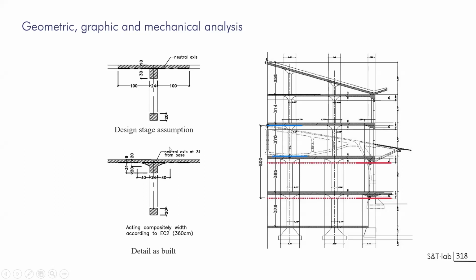So this is the principle that was developed at the same moment for the stiffened arch bridge, in which you have a deck that will be quite stiff and an arch that will be perfectly funicular. So this is the same principle that will guarantee that you can sustain bending force in it. So now, what about the geometry? You see that the top of the roof is just at the limit of the floor of the third floor. The lower part of the funicular will be just at the top of the lower floor. So these are the limits for the geometry.